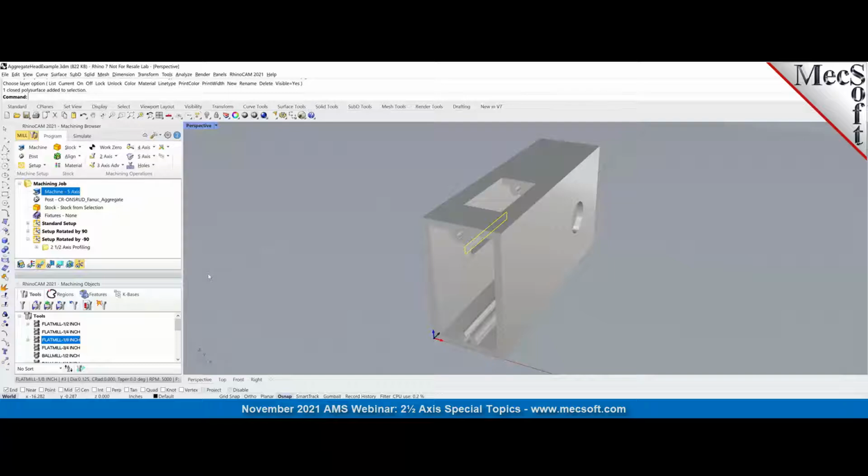There was another question asking about how to program the sharp corners in the pockets. That's one thing you can't do necessarily in CNC, is to actually create a sharp corner with an end mill. The best way to handle that would be a smaller end mill, just for the corner? Yeah, because of the radius of the end mill, you're going to leave that corner. In metal machining, if you want really sharp corners, people use electrodes.